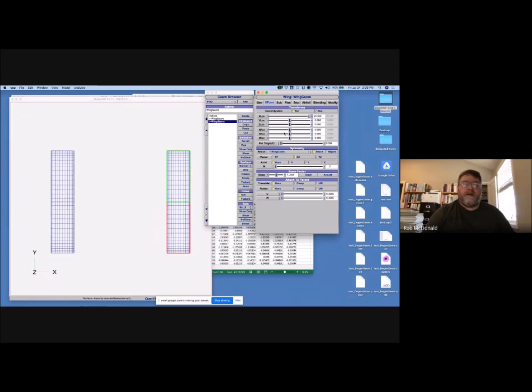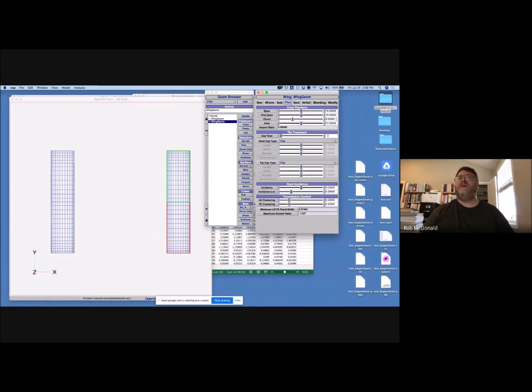It takes some work, but it's certainly possible. There's not a single call that just says, sweep this parameter from A to B and run a bunch of cases and collect the data and put it in this pandas container, right? We don't have that high level of a function call, but certainly you can change any parameter in VSP in a model, both the VSP Aero solver parameters as well as the geometric parameters, and you can access all the data. And so it's kind of a DIY, but you can write a for loop, you can change the parameter, you can track the data, and then you can create a plot. So there's not high level functions for doing design sweeps, but it's absolutely what it's there for.